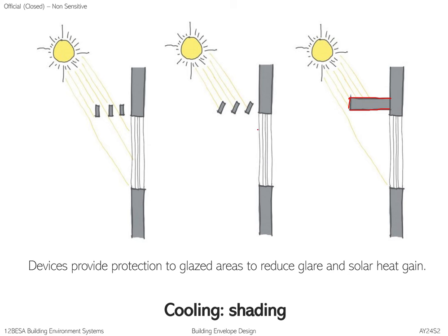So imagine if you don't have that. That's why you will realize that a lot of the condominiums are using full height glass, and some of them actually don't have this kind of sun shading devices. So as much as they use very expensive and high spec low E glass, when the sun comes, it still gets rather hot, and there's a lot of glare coming into the space. This kind of sun shading device balances the need to have diffuse daylight versus the need to exclude solar heat gain and reduce glare.